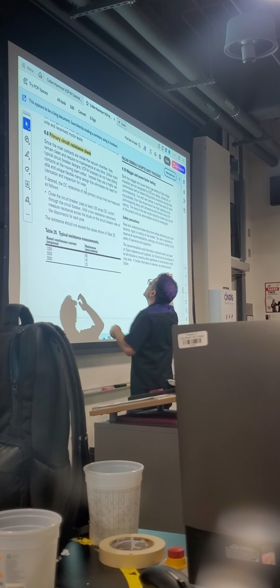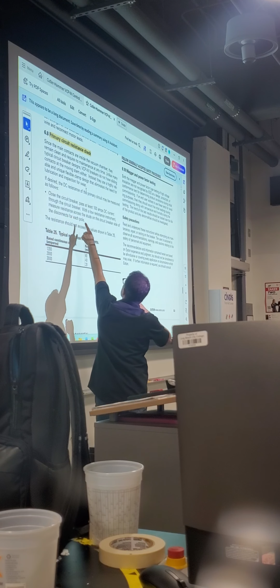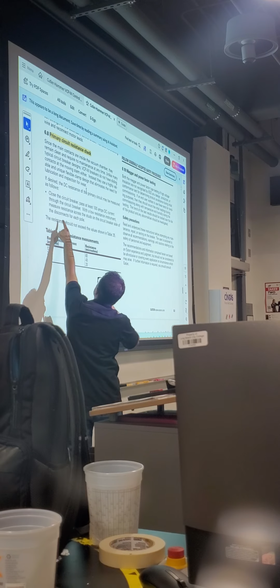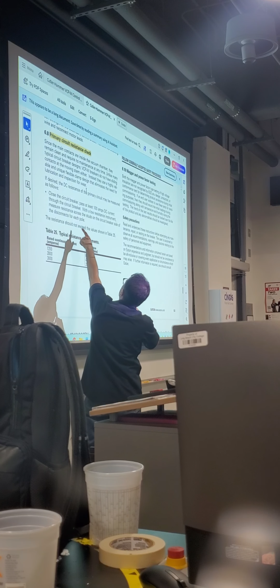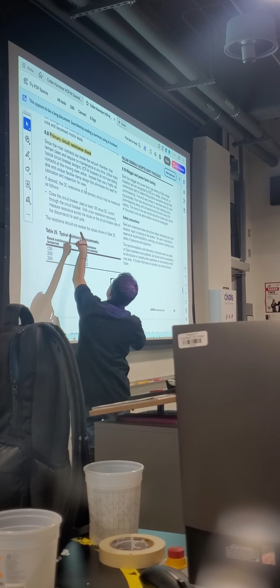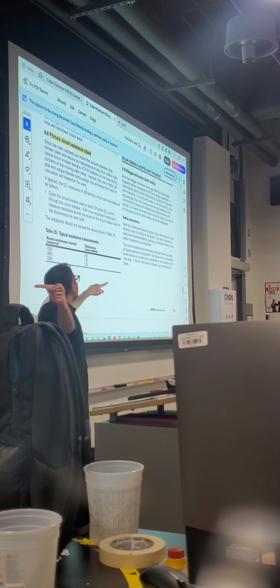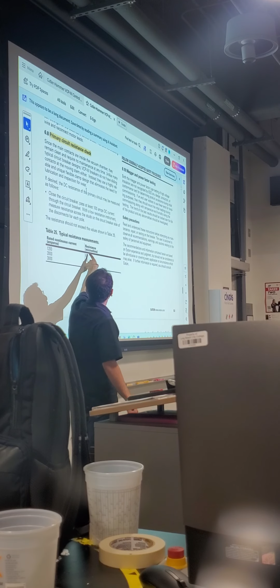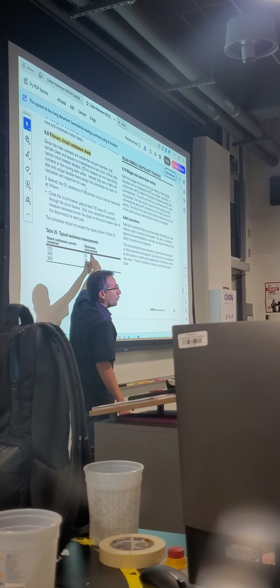Now, if you read here, it says for WCP breakers, you are supposed to close the breaker, pass at least 100 amps DC through the circuit breaker with a low resistance instrument or DLRO, and measure resistance across the studs on the circuit breaker. The resistance should not exceed the values in this table. The breaker we have is 1200 amps. So for 1200 amps, your contact resistance is not supposed to go above 60 microohms.